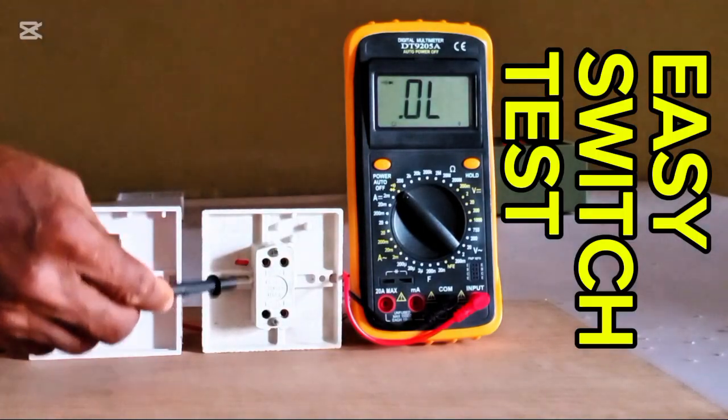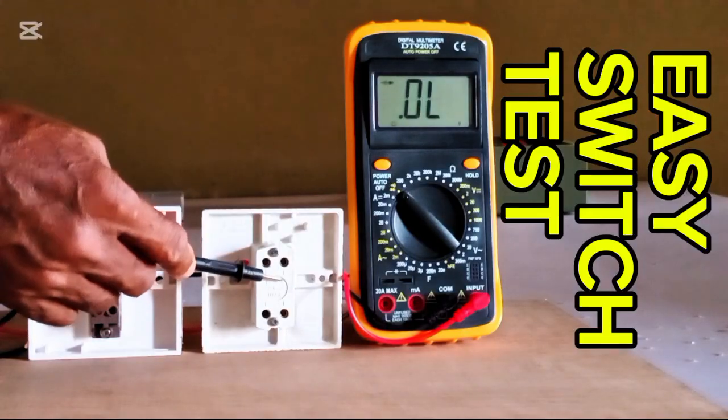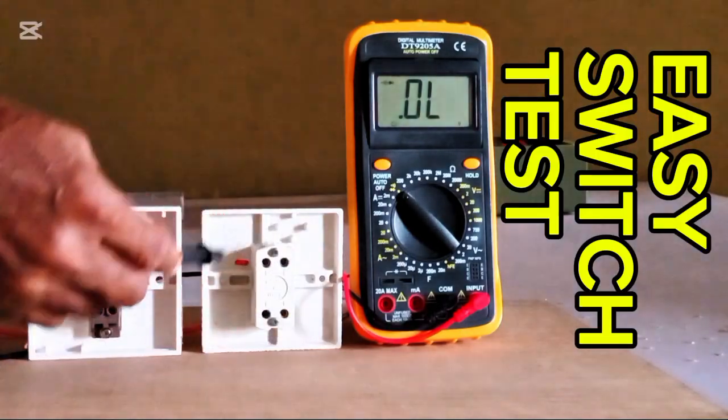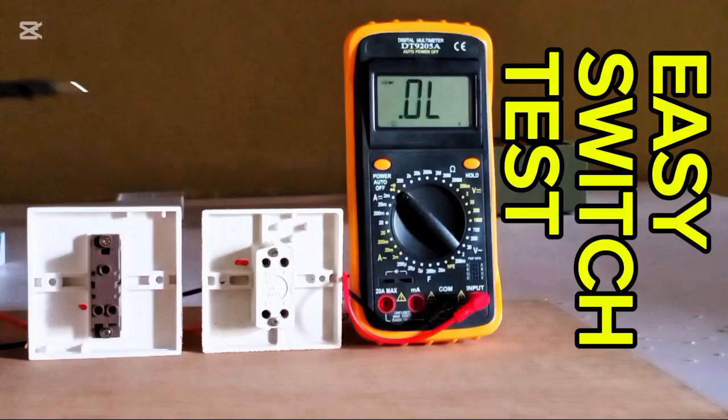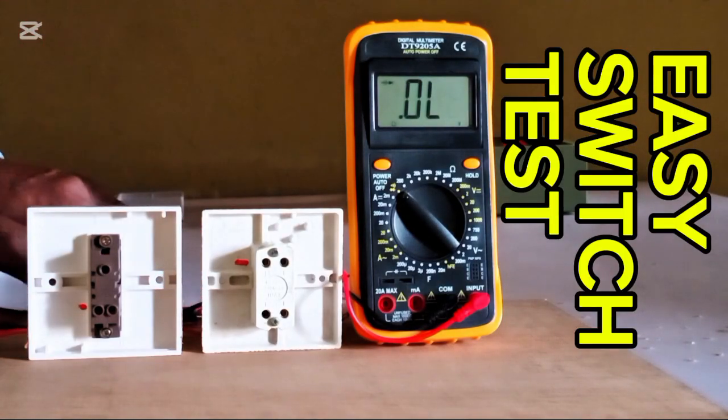So if the two channels are shorted, then it is faulty. If the one that is meant to read fails to read, it's also faulty. So these are the conditions in which the switches will appear for us to conclude that they are good for use or not good for use.